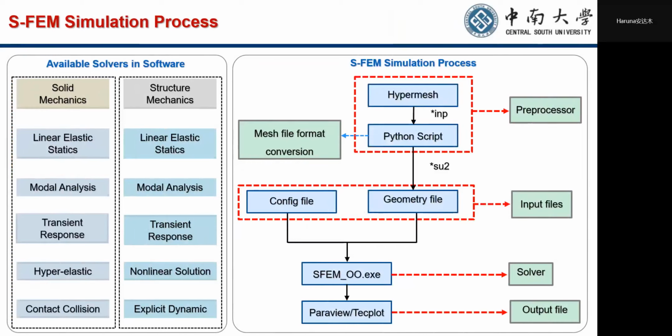Here are some available solvers in the SFEM code, because unlike software like Abaqus and ANSYS, the SFEM uses in-house codes. So we have to perform some pre-processing and post-processing by ourselves. The code only runs the simulation. It doesn't display results, and we can't manipulate our geometry or our mesh in the code.